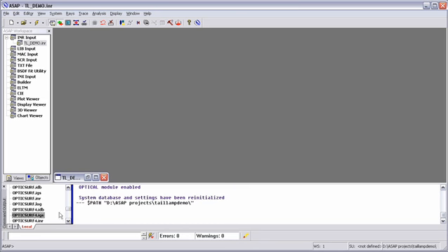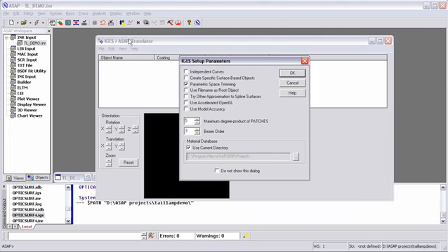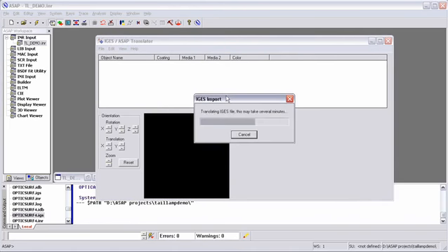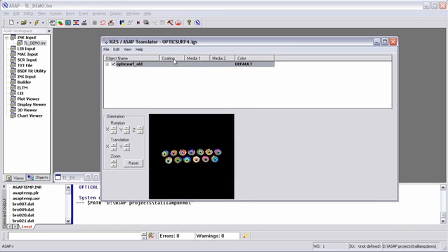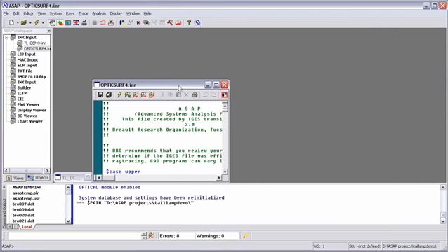If you recall, we saved our file out of Rhino and we called it OpticSurf4. So I'm going to double click this, and this is going to bring up the IGES translator. We can accept the defaults here, and you can see that we've got our optical surface. Now this translator offers you the opportunity to do material assignments within the translator. However, I'm going to skip that step, and we're going to do the material assignments inside our script, and I'll show you why when we're finished.